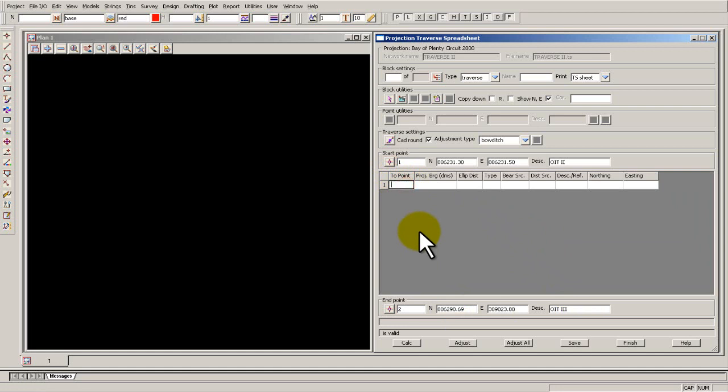So, and then in here we're going to go to, now that's putting in there 0.2, but I've already put that in as the end coordinate, so I'm going to put in there 3, because that's going, and we've got 65.31 for the bearing and 81.37, and that is a traverse, and we're going to iron spike 1, enter, and then we were going to close off on 2, which should be 61.31 again, and 81.24, enter, again that's a traverse.